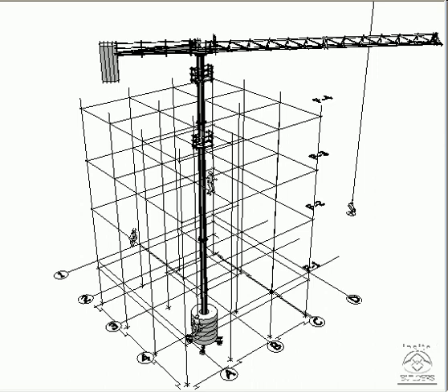First, all design drawings using beams and columns for the general building construction have column line designators. These are addresses that are referenced during coordination of the drawings between consultants. It's also useful for moving and assigning work in the field, where a contractor can position people according to column lines. Go to floor 2 between column lines 3 and 4 along column line A. These are therefore addresses used between subcontractors, equipment operators, and the design team.